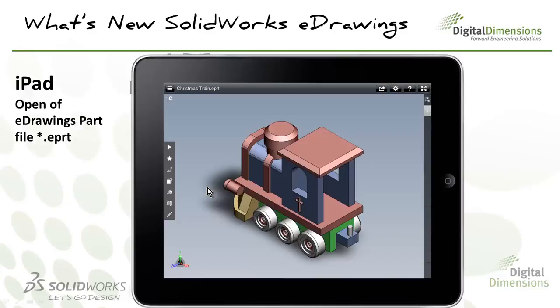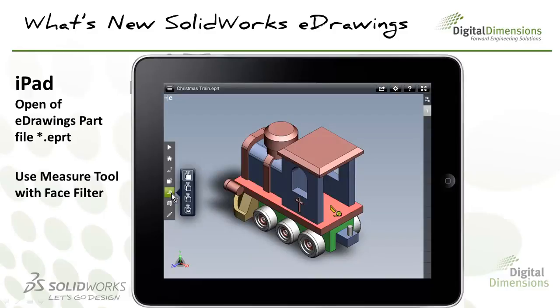And from here, the other goodie that comes packaged with eDrawings Professional is the ability to measure. And with Measure Tool, I'll go ahead and measure between faces. Maybe I want to measure between this face and this face here.